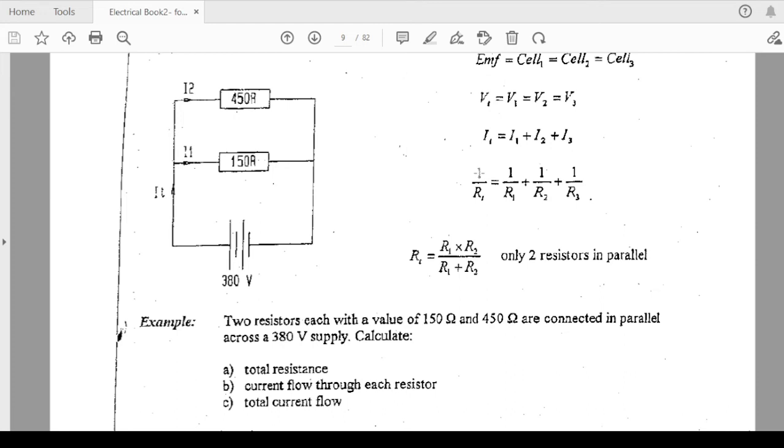Yes. You are manipulating the formula. So whatever answer you get on your right hand side, you add the three fractions. If the answer is 0,002, take that 0,002 and divide into 1, and that is your final RT. Because I see students just leaving RT as 0,002. They are forgetting to cross multiply. You have to do cross multiplication to get RT, the subject of the formula.